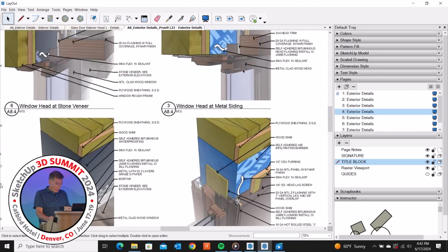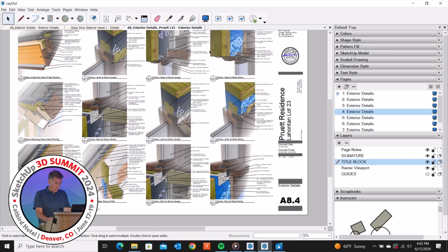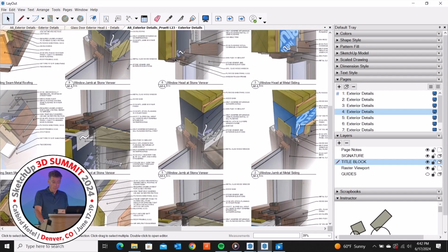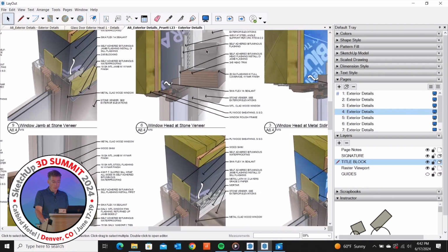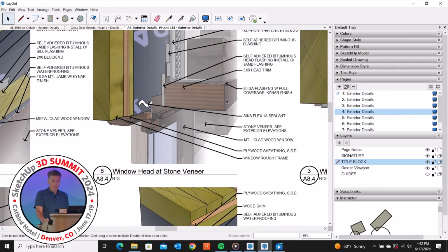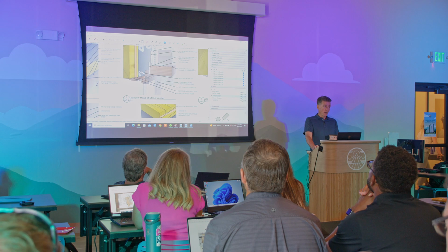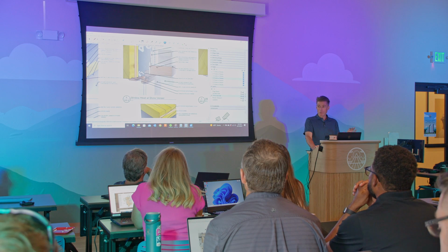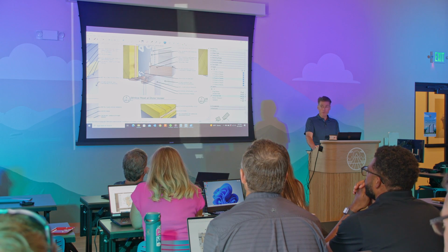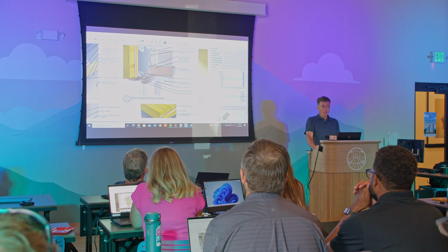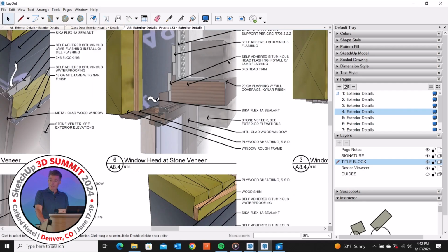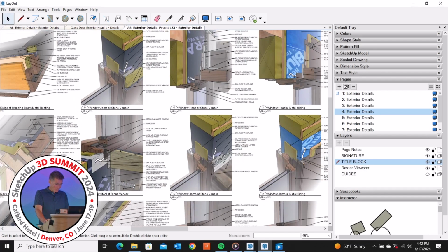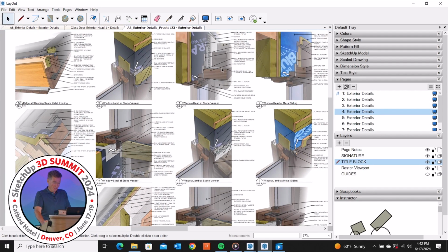I'm wrong. So we do have one here where we have metal siding, and then we had some where we have stone veneer. But again, in this case, it was wood. This was a custom detail just for this job, so it had a really narrow piece. And these are a pain in the butt to install. They hate that because we drill with lags straight through to keep that profile, and so we're using 1/2-inch lags by 8 to 9 inches to get it into each stud. They love me when they do that detail. At least they don't have to plug it because we flash over it.